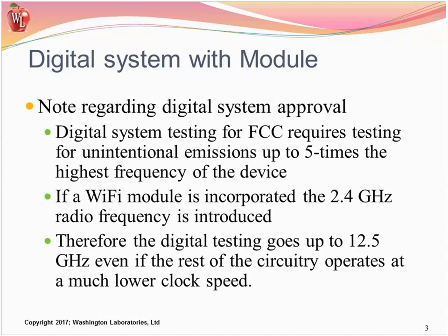This is not unusual, but this particular approach is not very thorough throughout the industry, and the FCC has made this an issue. I know that was part of the discussion by Steve. Remember, the approved standards have to be dealt with. The use of Wi-Fi communications is the most typical, with FCC Part 15.247 applicable for the U.S., RSS 247 applicable to Canada, and it's the ISED, formerly the Industry Canada group.